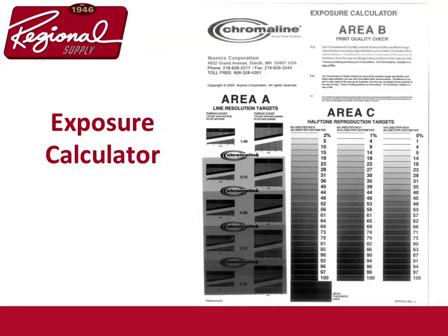We do recommend that over the period of a year you use an exposure calculator every so often to make sure your exposure times are correct, because different mesh counts, white mesh, and yellow mesh all have variables that take different times to expose.